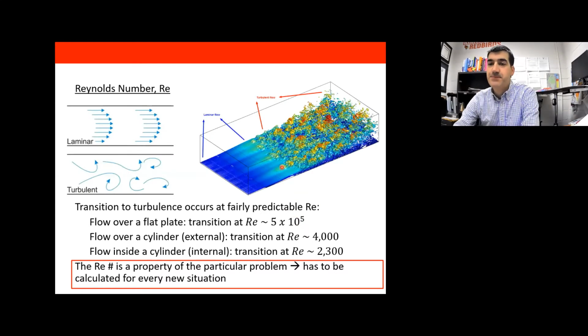So here's a picture of how fluid can transition from laminar to turbulent. The longer the characteristic length, in other words, the longer the length of the solid surface over which the fluid is flowing, the more likely it is to turn into turbulent flow. Here you can see an example of that. Initially, if the fluid is flowing left to right in this direction, the fluid is flowing in a laminar flow, but then right about here, it transitions to a turbulent flow, and now the flow becomes increasingly turbulent with higher and higher Reynolds number.